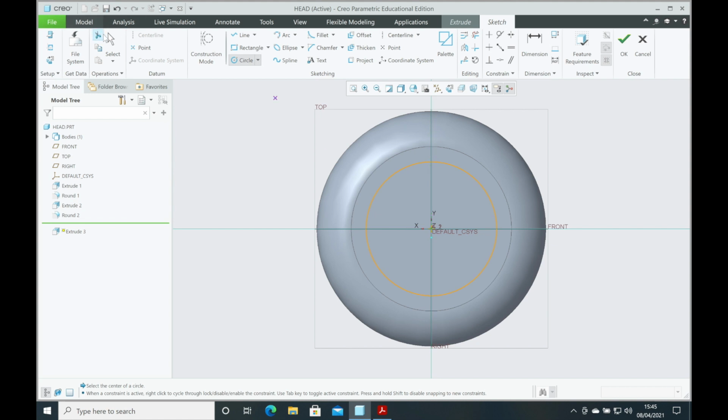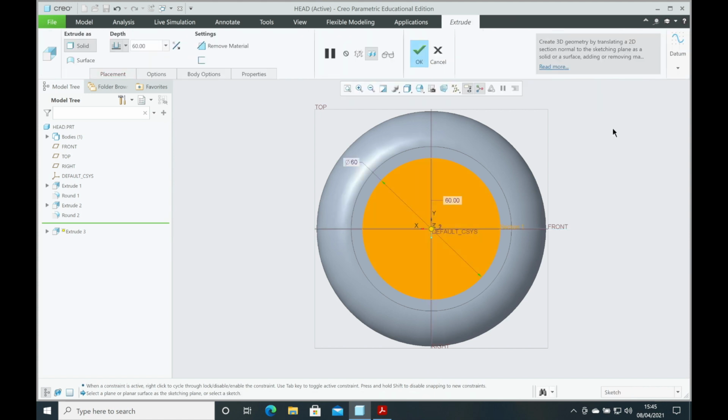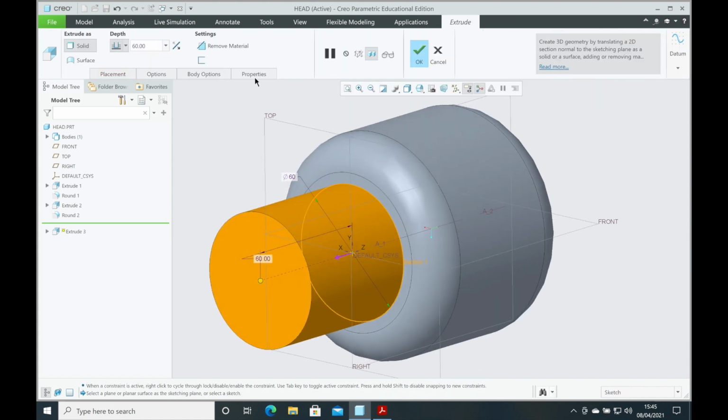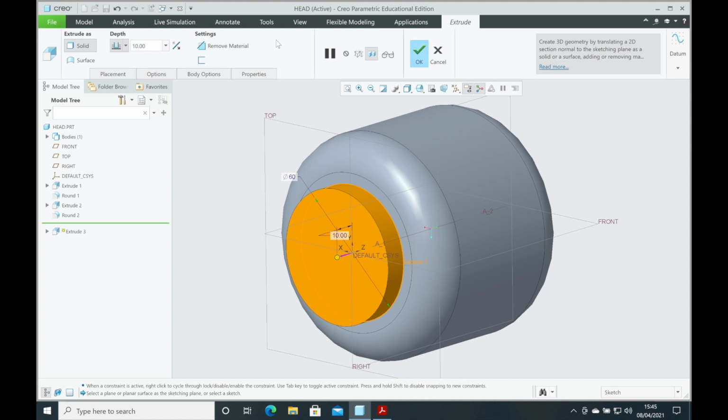Once you've drawn it, you're going to press the select button, and remember, it will then change colour. So it's gone that pinky purple colour, and I changed the number. This time the number needs to be 60, so it's slightly bigger. We press OK, and I'm going to put the dimension that it sticks out. So remember, it was the scroll wheel there to move it around to 10. So I'll type in the number 10 and press OK.